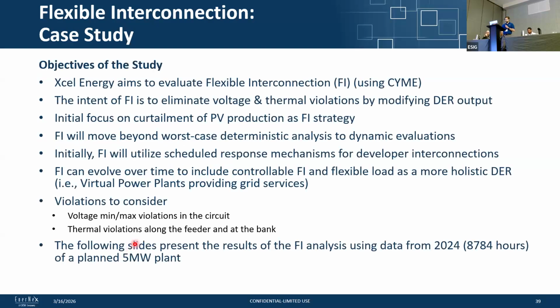So pretty straightforward. Some of the objectives that Xcel was looking to solve was to evaluate flexible interconnect on a certain circuit feeder so the substation wouldn't have any issues. So the intent was to eliminate primarily some of the voltage and thermal violations that would maybe be introduced through the flexible interconnect plant, and it was a PV plant. And we do that by modifying some of the DER output.